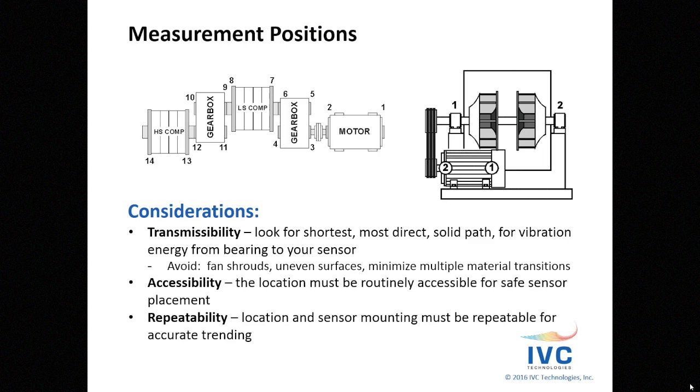Places you'd want to avoid: fan shrouds, uneven surfaces where your sensor might rock. Minimize multiple material transitions, a bunch of seams or a bunch of welds, things that get between the sensor that's taking the measurement and the source of the actual vibration that you're trying to measure.